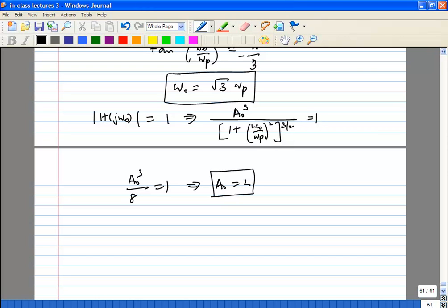My question is, if I just see the transfer function, it will never be satisfied that it will oscillate for h of s more than 2, because h of s will not be equal to 1 at that point. So if you need to do that analysis, you'll have to look at the poles and zeros of the system and see exactly.